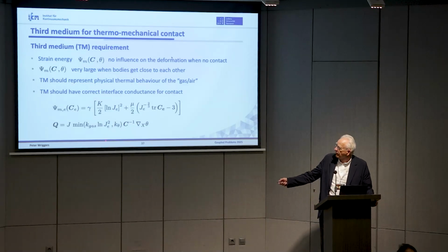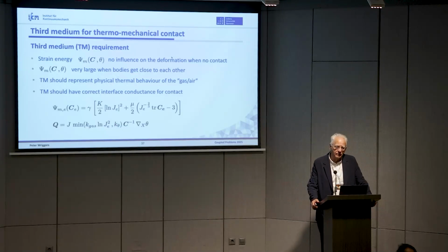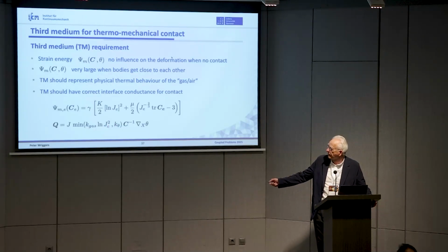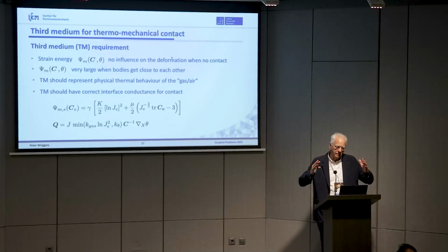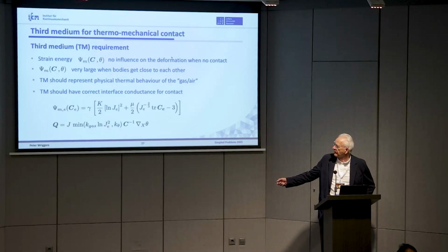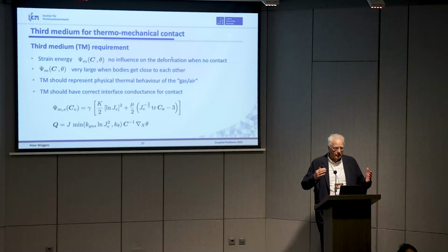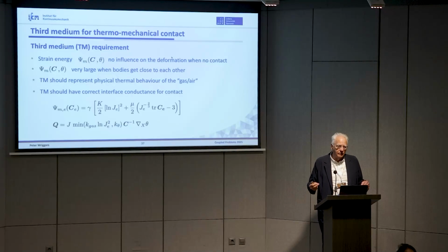So these three things you have to take into account. Here we only took into account a simple form with a pressure dependency of the gas conductance, which means that when it's squeezed together very much, it will get very high values. And so we stop here at the conductivity of the solids. That's the idea with this kind of law.